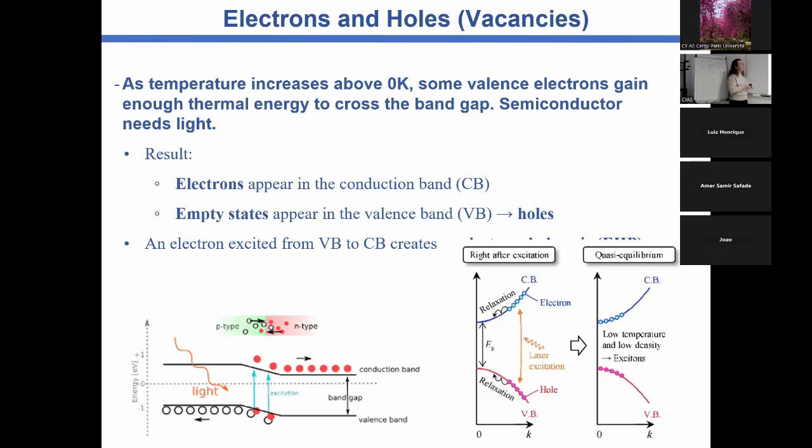For instance, in OPV or perovskite photovoltaic devices, we have electron transport layers and we have hole transport layers. So we must distinguish those two kinds of carriers. Each one has specific properties. So we cannot use the same material as electron transport and hole transport because they have different properties.